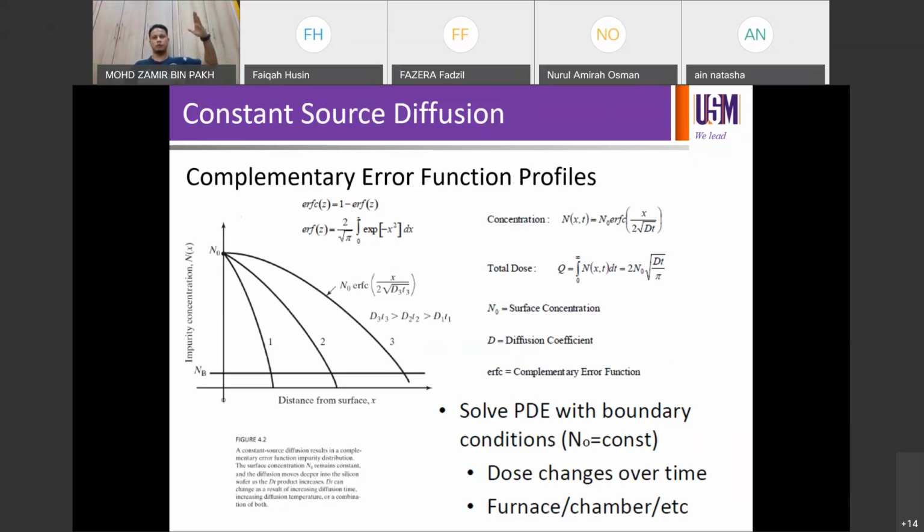So from minute 1 until minute 60, you're going to have your phosphorus coming in contact with silicon surfaces to be able to continue the diffusion process. It means throughout the process you have a constant source of phosphorus coming in.